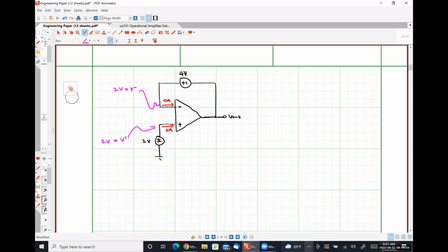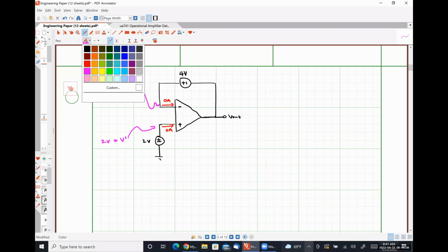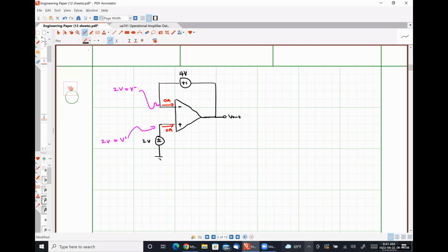Okay. So where I'm going to apply Kirchhoff's voltage law is like this. So I'm going to make some things maybe a little bit more obvious here. Let's do this in orange. So our output voltage, as I mentioned before, all of our voltages here are nodal voltages. So our output voltage is really the voltage measured at the output terminal with respect to ground, which is the same as this voltage. Is everybody okay with that representation?